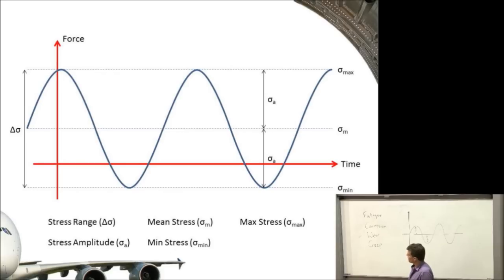Okay, we have to be a bit careful because some textbooks will interchange stress range, stress amplitude, delta sigma. Depending on where you're looking, you've got to be very, very careful that you've used the correct stress range in your formula. I will be very careful about defining it in exams or in tutorial questions about what I mean. But if you're applying it to a problem somewhere else, you've got to be very careful that these are defined correctly for your particular case.